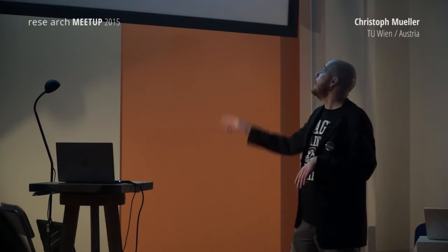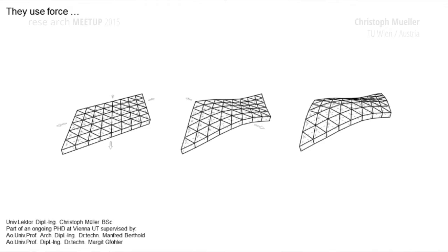What you would need is to deform it at least in one direction to get a stable shape. Imagine a sheet of paper. When you bend it, it is stable in one direction, and if you double curve it, it is stable in both. Another possibility, of course, would be to double it up, having two layers, and a third possibility, doubling it up and having connections in between them.